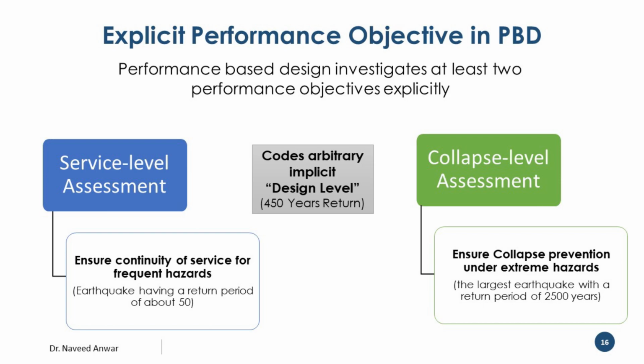One is the service level earthquake. So then you say, okay, fine, if you want your structure to be completely serviceable, this is the earthquake that you should be checking it for, which is the frequent one. It will come once or maybe twice in the lifetime of the structure, but your structure will be completely serviceable if you want that. So this is one level of assessment that we can carry out.